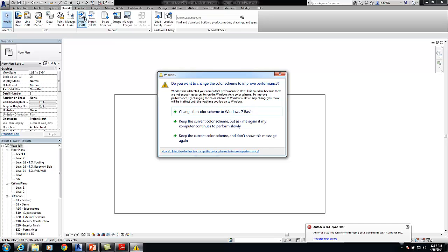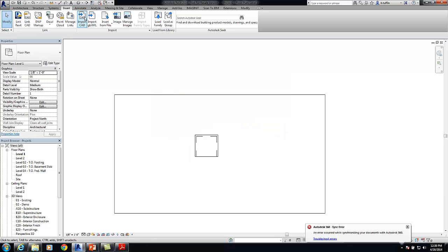There's a lot of programs out there that claim they can, and when I say they claim they can, I expect it to meet SEAT guidelines. I expect it to be fully constrained, 2 reference planes for every face, multiple levels of detail, and all parameter data to come across. No, nothing does that right now.